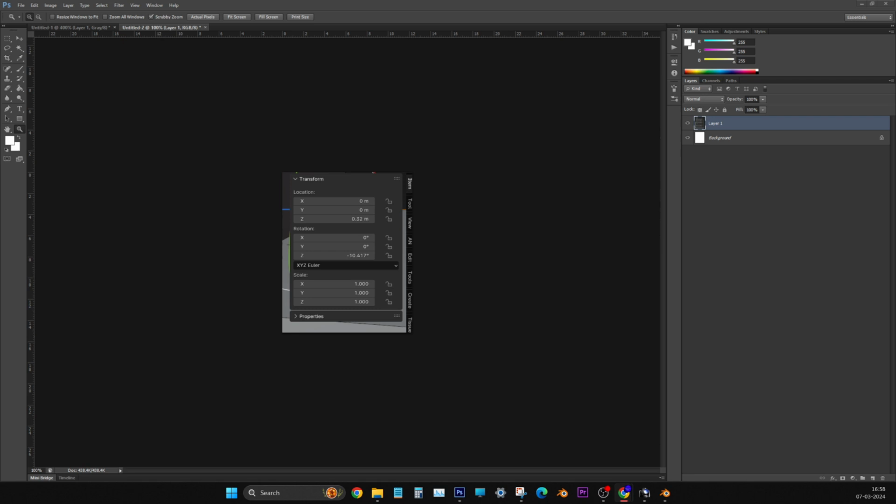Now, I told you that for making a spiral shape, a special shape, we have to bring in a third party, that is an empty, which has no mass and no volume. Still, we need it, because for an entity we need a presence inside the outliner. Now go to Add in the submenus, left side. Come down, Empty. Plain Axes, the first one. Now don't move it anywhere. Here also don't give any values.